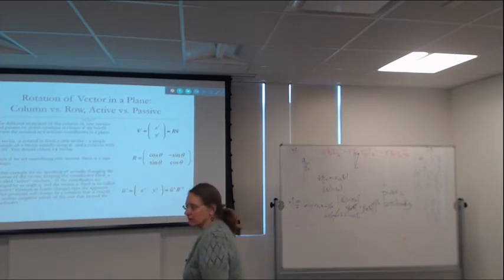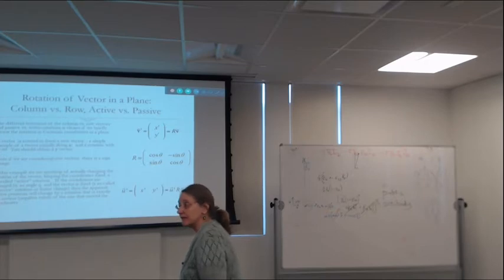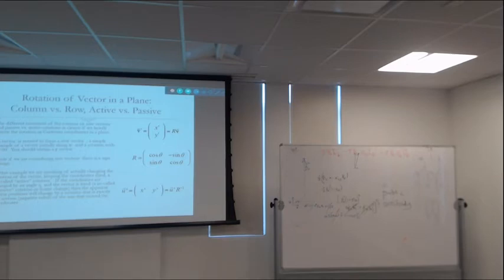So these are so-called active rotations. What that r is representing is that I actually sat in a fixed coordinate system and moved my vector. That's an active rotation. In the last slide, we said we need a lot of rotations, but we didn't need active rotations. We need so-called passive rotations. That means the vector doesn't change anything. It's just the coordinate frame that's changing. We're moving things from one coordinate frame to another. And it turns out that if I'm talking about a passive rotation instead of an active rotation, I can put a direct substitution.